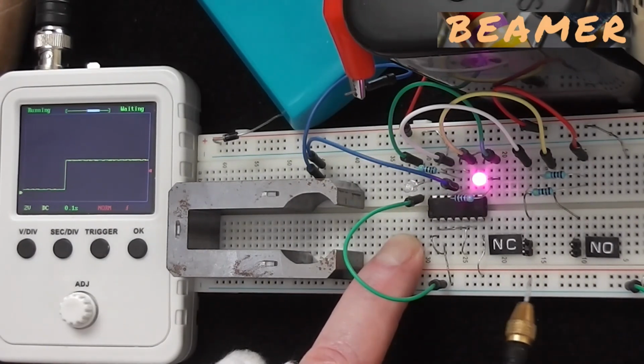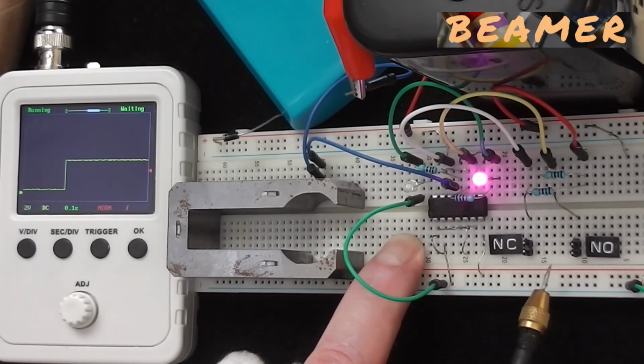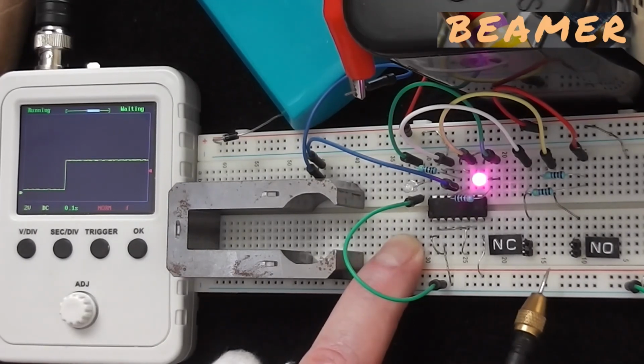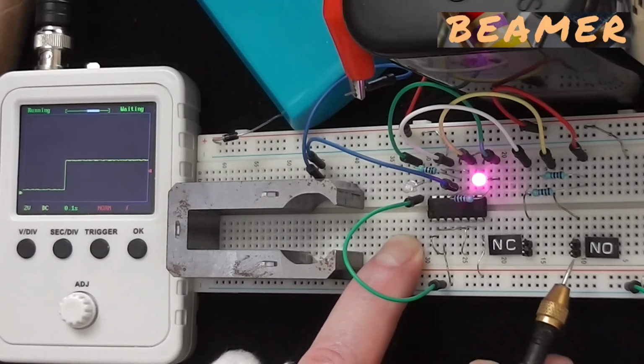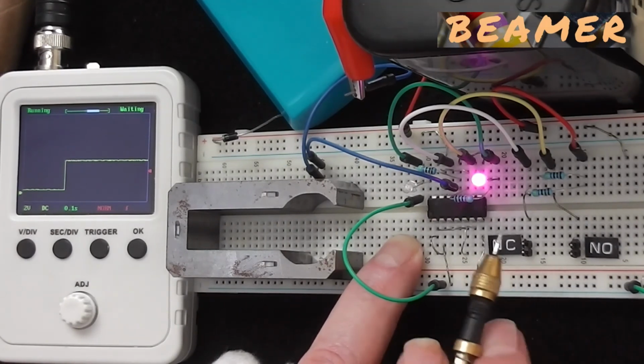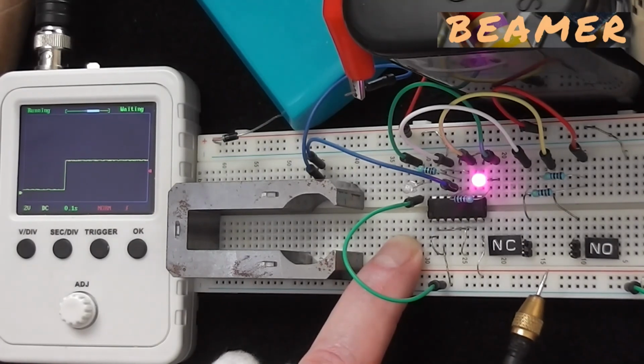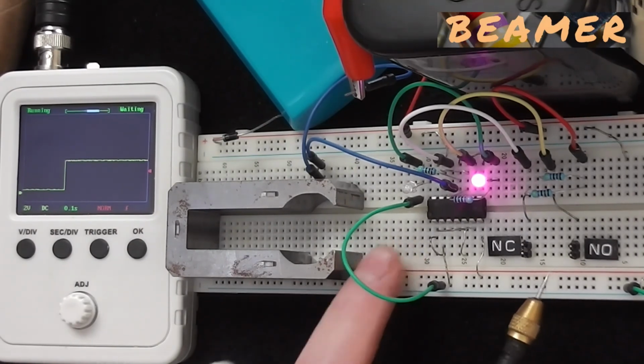So this would make a micro switch live a very long time, because the current going through the contacts is reduced to about, I would think, 1 milliamp. You can adjust it to whatever you like, but I think 1 milliamp is what I chose here. And that means its life is extended. And of course, if the contacts become a little hairy with time, then because there is this flip-flop in the circuit, this micro switch would have to wear considerably before it reaches its end of life.